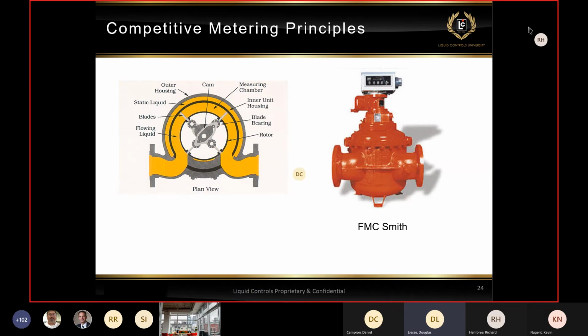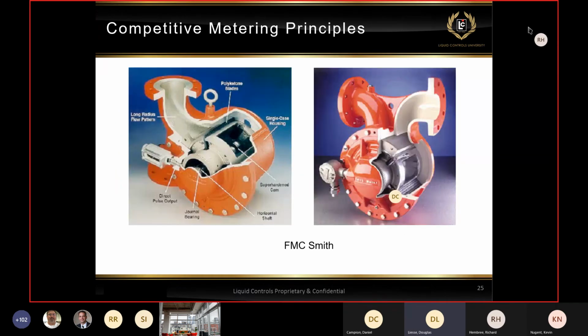That bearing is located at the bottom here. And that's also an area where it's a stagnant product liquid. If there's anything in the liquid itself, it settles out. It'll settle out in that area, causing that bearing to fail. So they came up with this design by going horizontal with it.